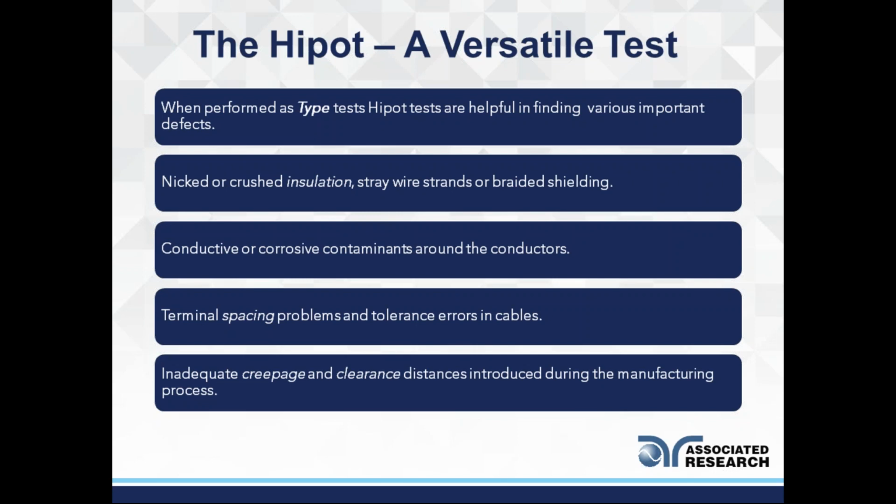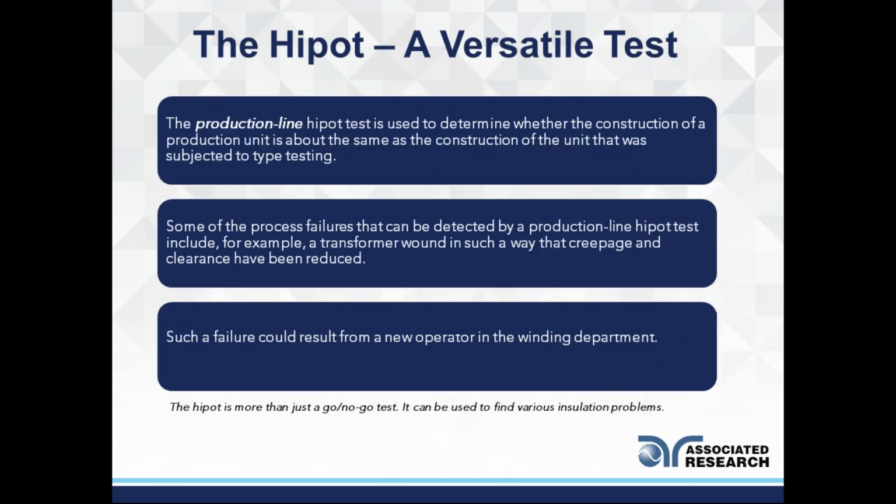It is during the design phase where the Hipot test, considered a type test, is performed to make sure that the product you're designing is meeting the standards you're trying to comply with. Now, the Hipot test, like I said, is also performed as a production line test.